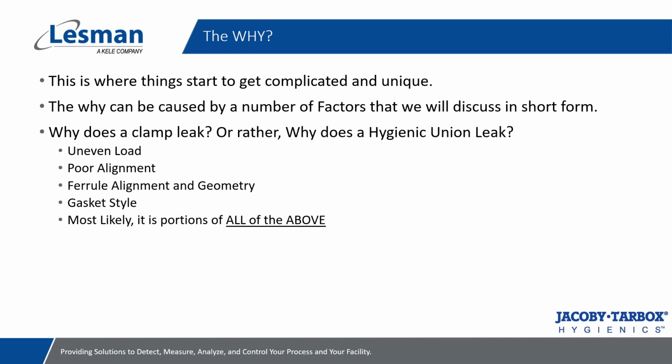To make a modification to that vessel, that tank has to go back through all of its certifications, right? So if we're planning on the solution being, hey, let's cut that ferrule off and re-weld another ferrule on and see if we can do it without warping it this time, that is a much larger problem than that solution sounds to be.